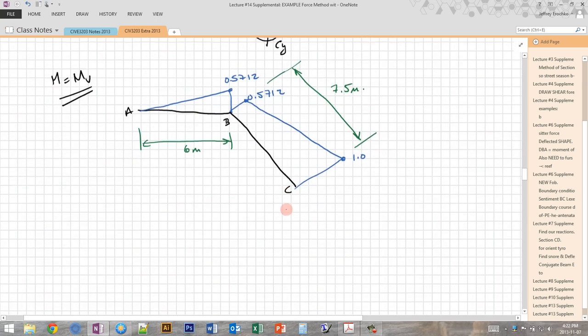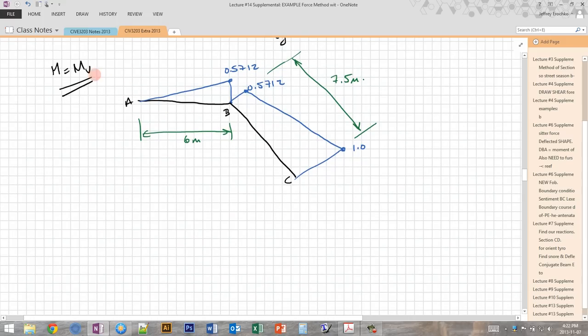So this is the exact same system, which I've copied here. And the virtual moment is the same as the real moment. So this is the same for both systems. So now we can do our virtual work, internal. And again, so now this time we're going to have a triangle times a triangle, because the same on both, and a trapezoid times a trapezoid.